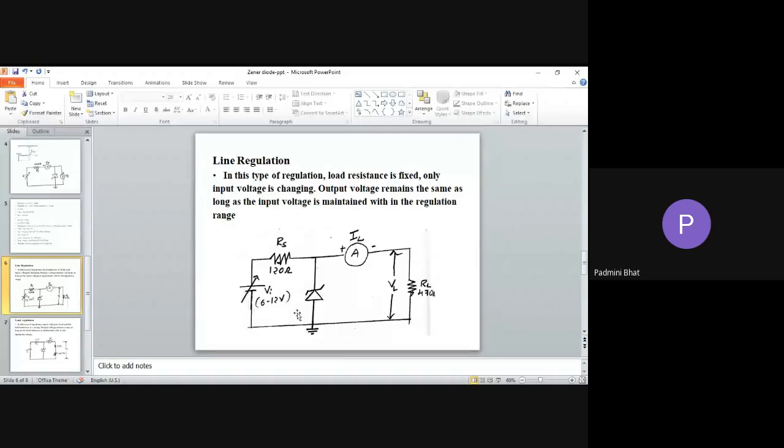Now, we were talking about the line regulation. We need to see, this is the permissible level. What happens if a value outside this range is given? So try giving 2, 4, 6, then till 12, then 14, 16. Only so much is sufficient. You observe that the current variation is fluctuating for the outside range. I don't say that it remains very constant, but whatever varies is also in the microamp level within this range.